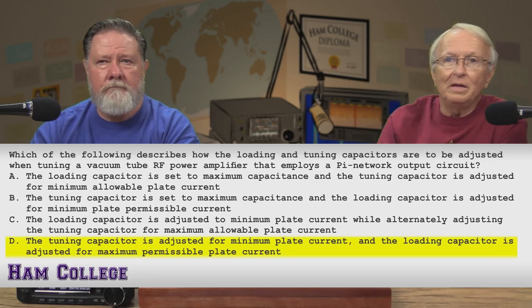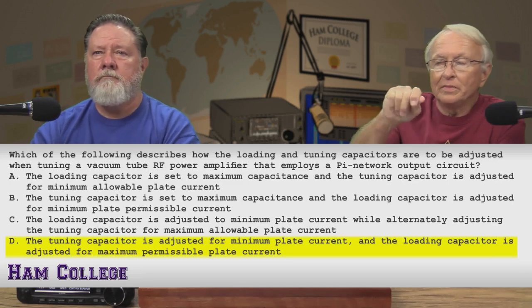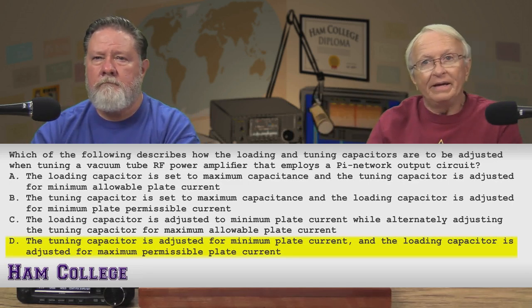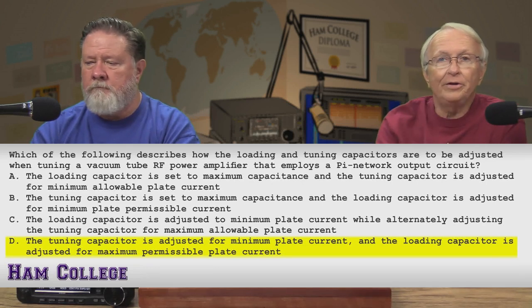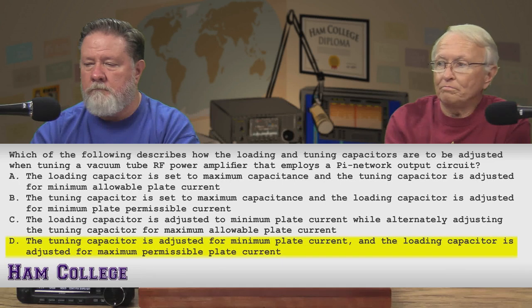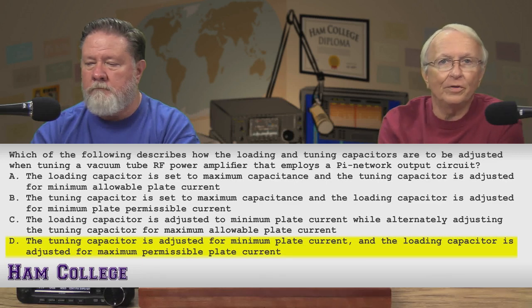But you want to dip it, or find a dip, or where you've got minimum plate current on the tuning. And I go back and forth between the two. You don't have to do it that often, but on your linear amplifier, whenever you change frequency on a tube type amplifier, you're going to have to retune it, unless you just slightly change. It's going to change a little bit as you change frequencies.